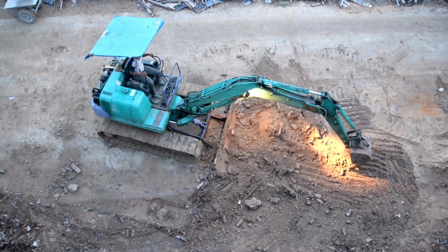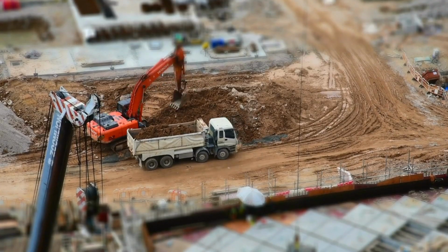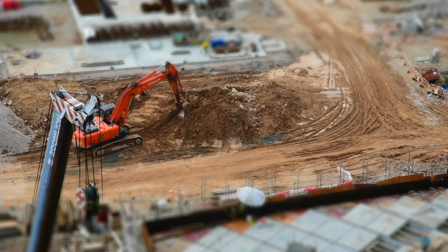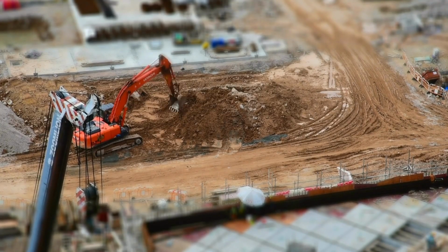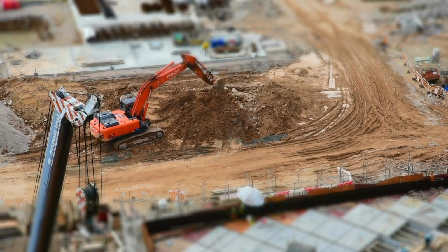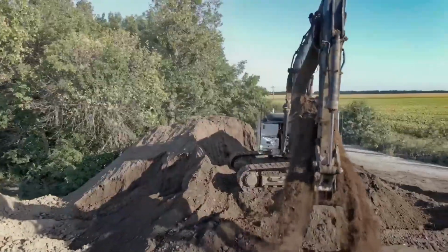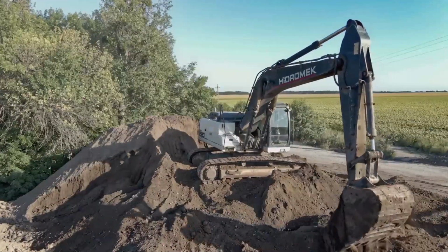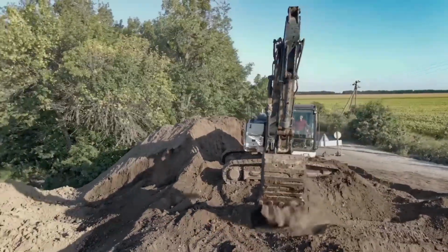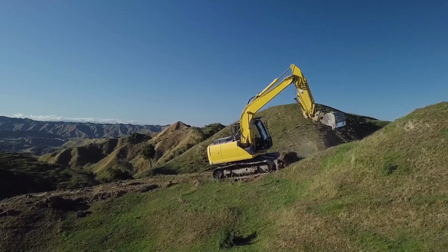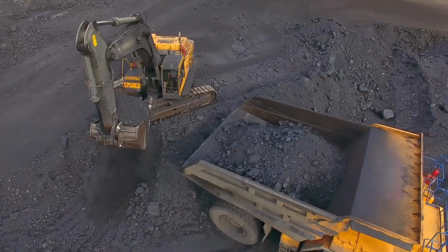An excavator front attachment can be understood as a mechanical chain made of rigid parts connected by rotating joints. Starting from the upper structure, the motion flows through the boom, then the arm, and finally the bucket. Each connection allows rotation, so engineers call this a serial kinematic chain. Most digging motion happens in one vertical plane, which makes this simplified model accurate enough to study how the bucket moves.